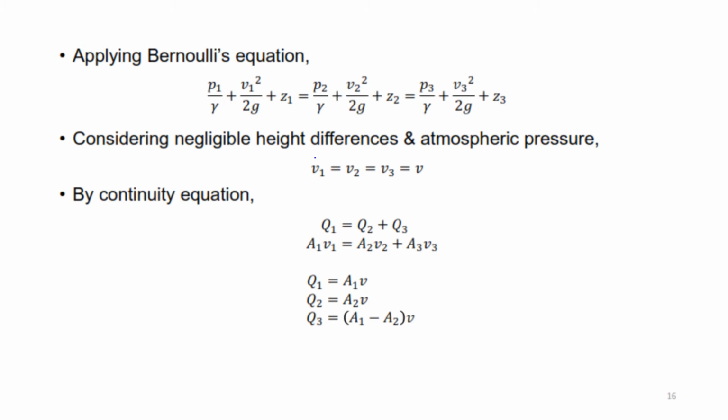Okay, next step we need to write down all the equations and formulas that are related to this question. So we need to write the Bernoulli equation, but we need to write it in terms of 3 velocities, because we have 3 velocities just now. We have V1, V2 and V3.